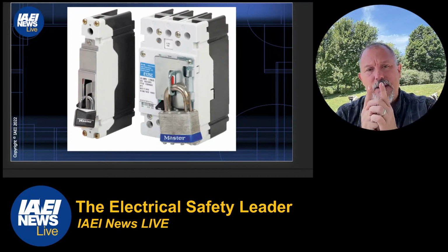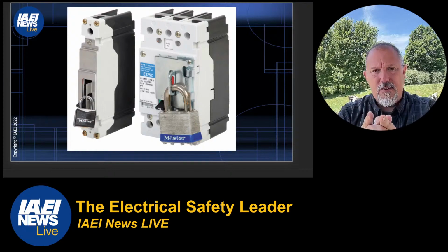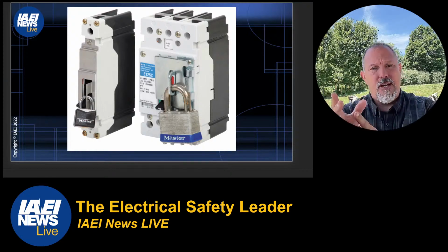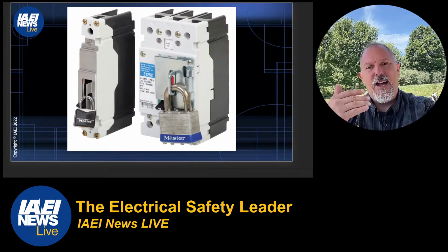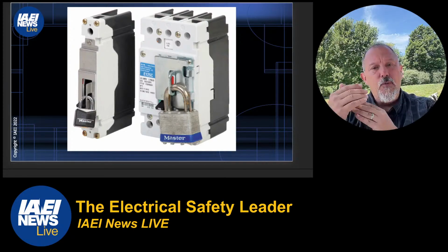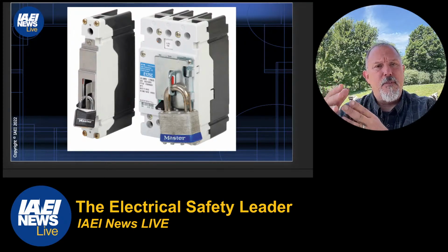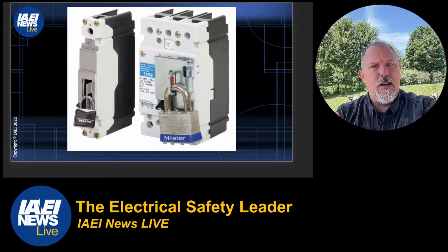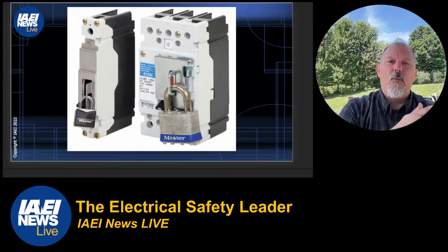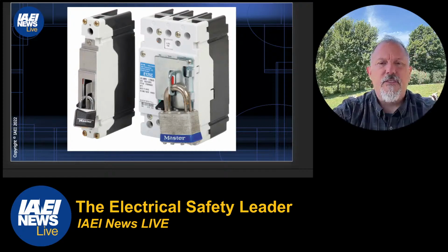But the other nice thing about these images here, these methods to lock remain in place after the lock is removed, so they would meet the requirements of the National Electrical Code whenever the provisions are in place that says these need to be lockable in the open position, and then 110 tells us that those provisions have to remain in place.